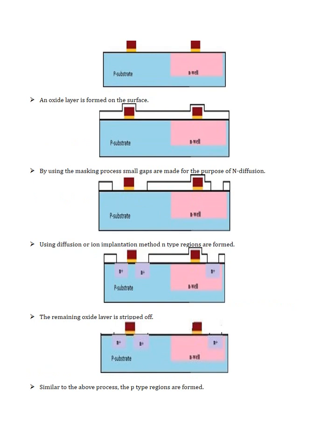So you can see that we require gates in two areas here. One region is for the NMOS and the other area is for the PMOS. In the N-well we will make the PMOS, and in the P region, where you can see the polysilicon gate region with this brown and yellow area, there we will make N-type material.